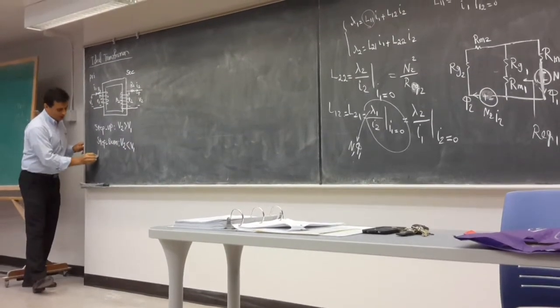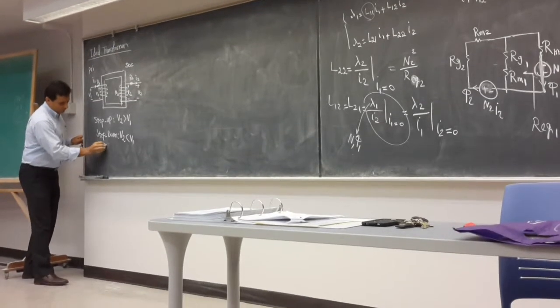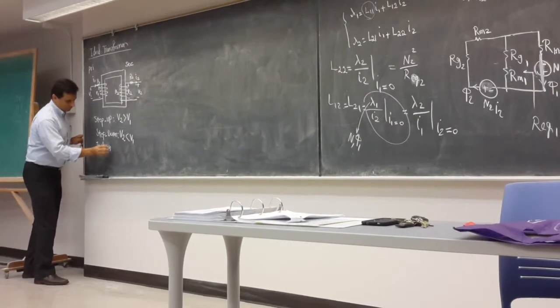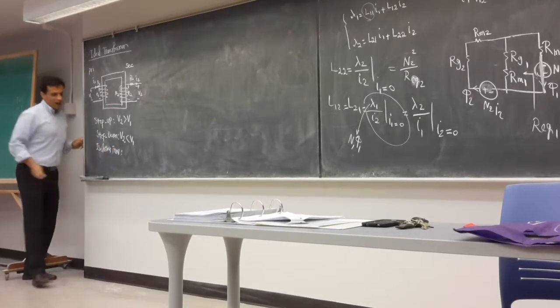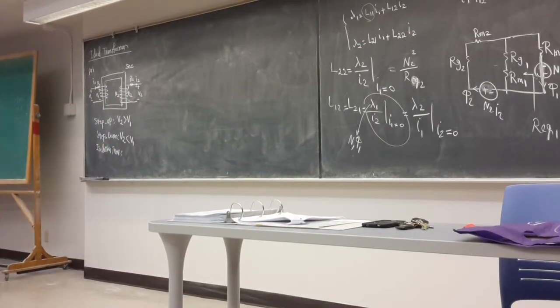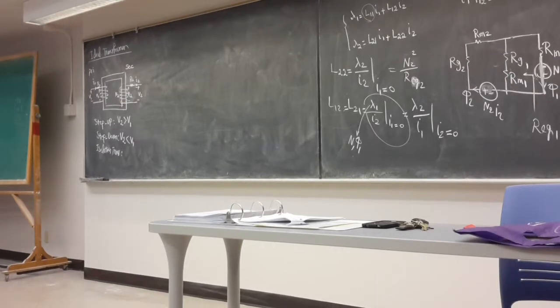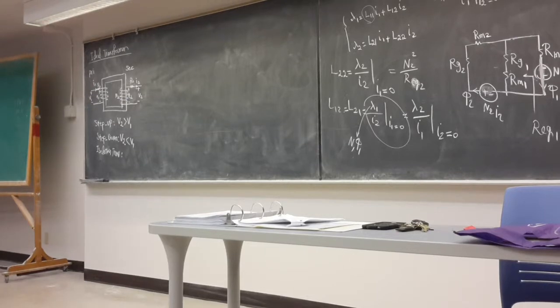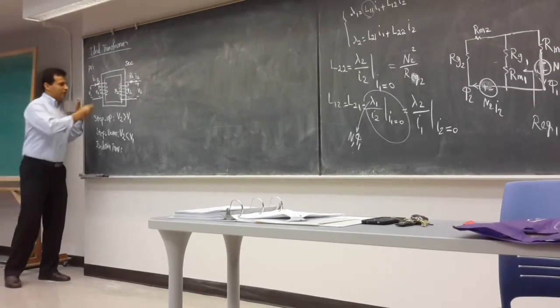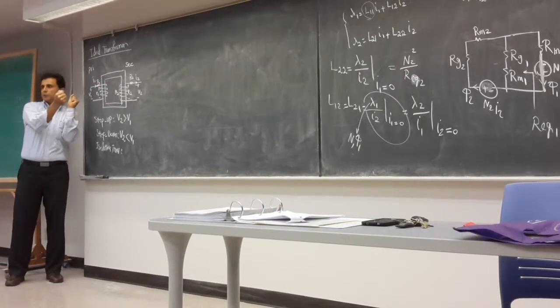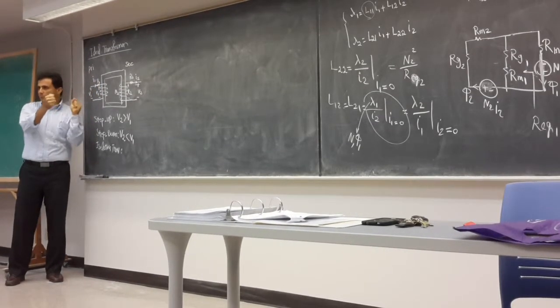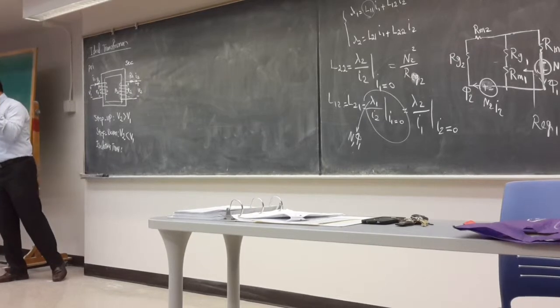If we have an isolation transformer, isolation means you want to separate 2 systems electrically. Magnetically, they are still connected together, because there is a flux going through these 2 windings, linked together through this magnetic flux, but there is no electrical point of connection.